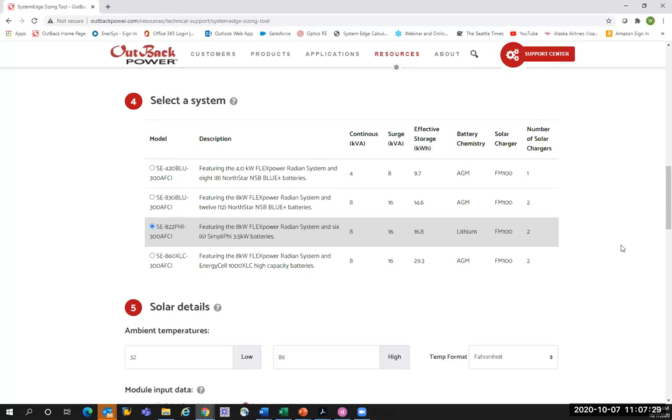But to be sure, on our inverters, I don't know about the SkyBox because they have surge, but the Radian has a 100 millisecond spec, which is like 5 cycles, and I've done tons of measurements on inrush current, and that inrush only lasts about 5 cycles. So if you look at the 100 millisecond spec on our Radian inverter, I think it's like 67 amps. So even one Radian would have been enough to handle the inrush.